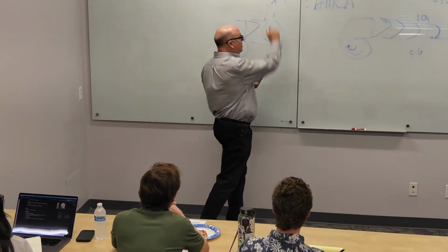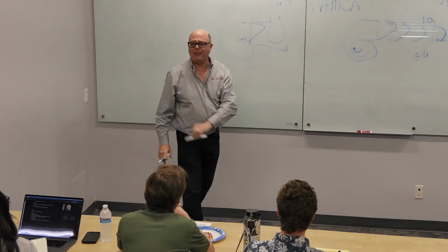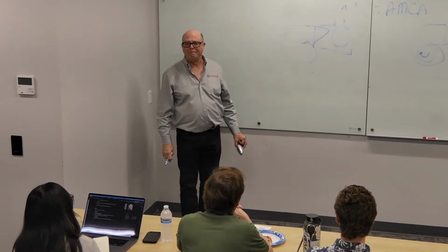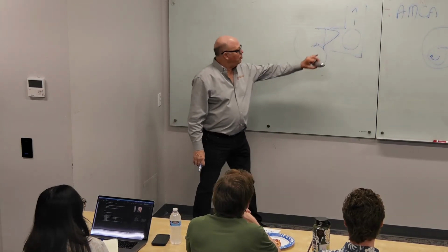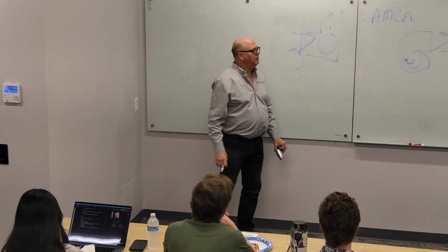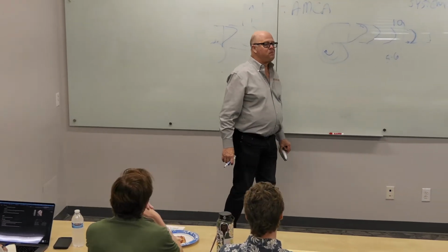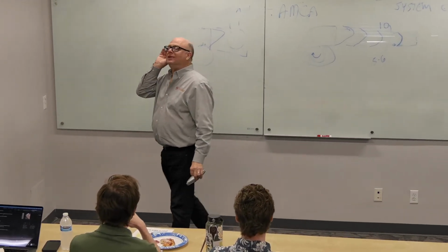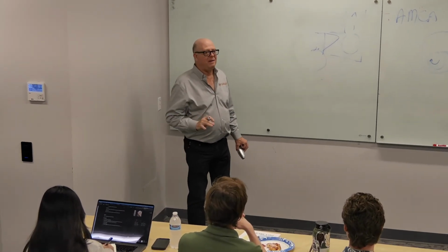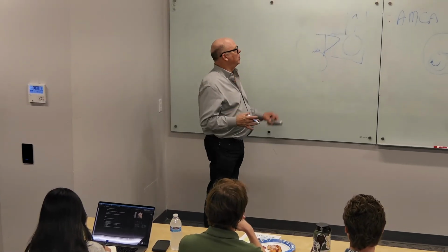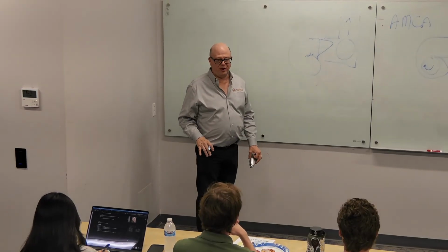Now maybe you've got a situation where you got a fan sitting here and the duct's got not much room and then it's got to go up. What do we do about that? Turning vanes. We can do things in the duct to make it better. Change the fan. What about that is the right answer, but what are we going to change on the fan? There's a word. Direction. Flip it. Higher static pressure. Well, we're going to change the configuration.